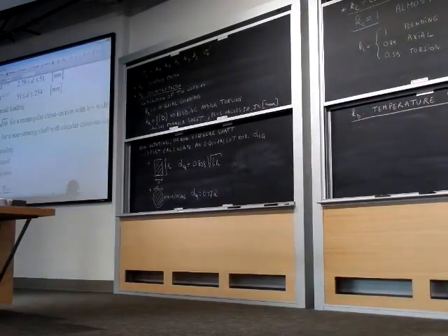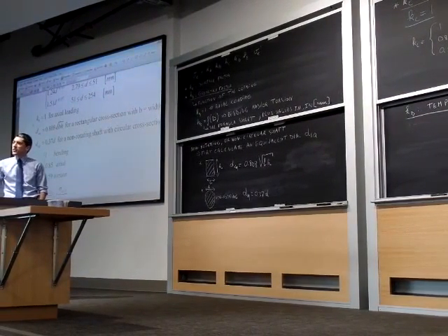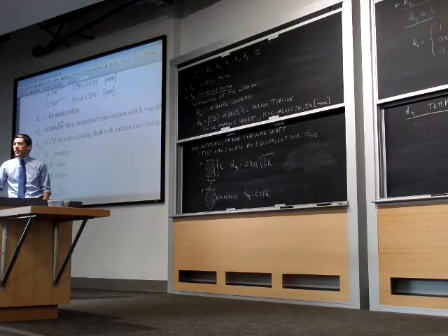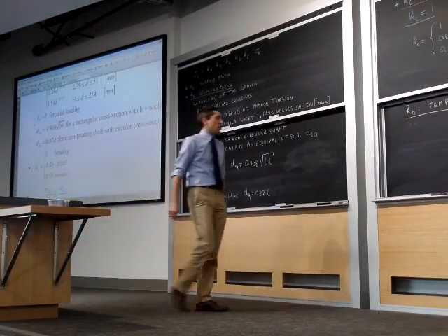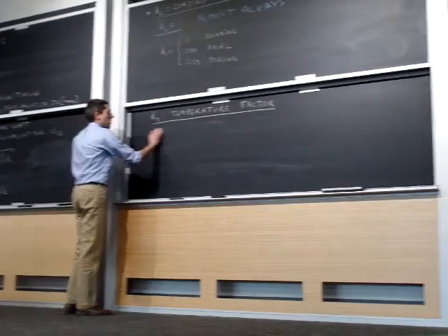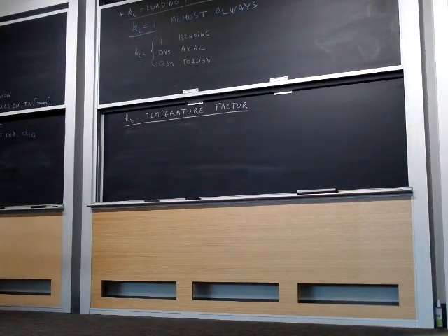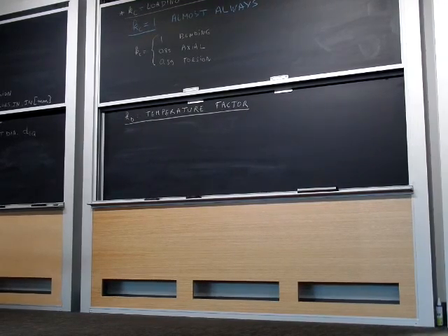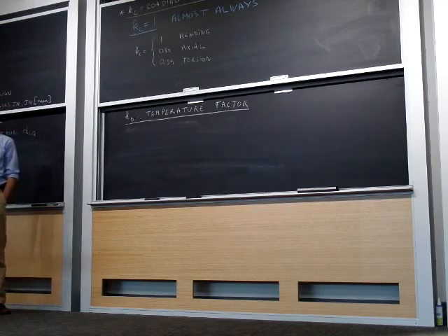I mean, it slightly depends on the alloy and stuff, but roughly. Is it 500 degrees C? Is it 3,000 degrees C? 6,000? 750? It's 1,400. Right? 1,400 degrees C is the melting point of steel. So most steels, and again, it kind of depends on the alloy, but it's good to know these rules of thumb. Steel loses about half its strength at 600 degrees C.